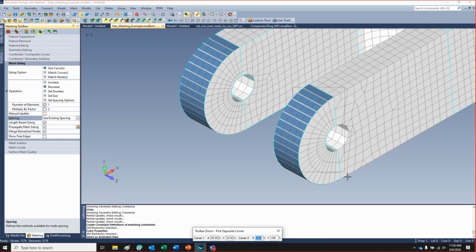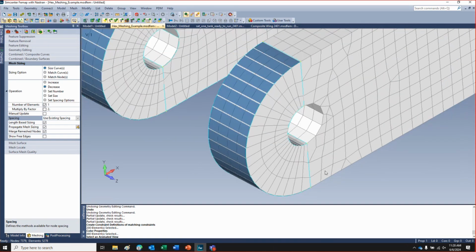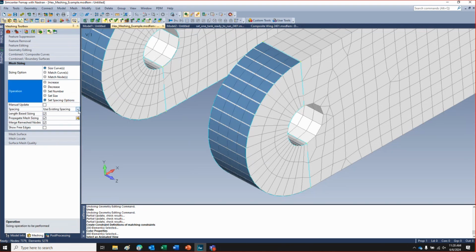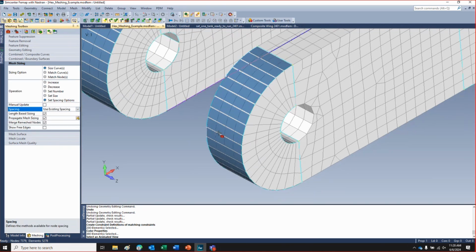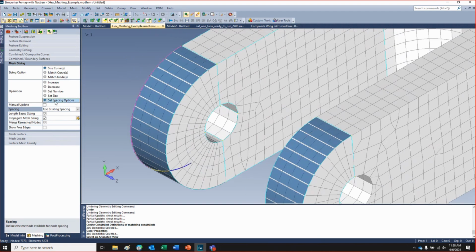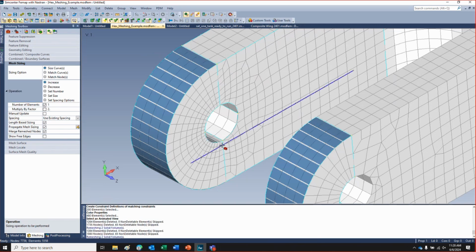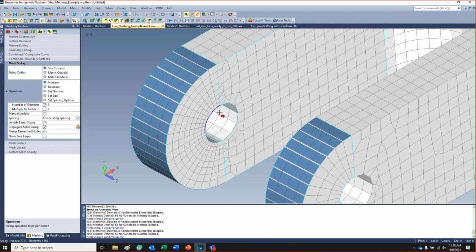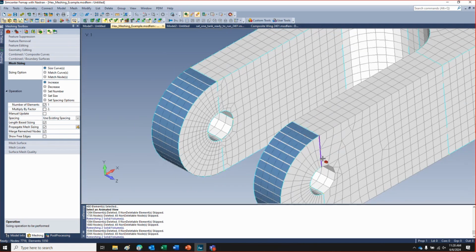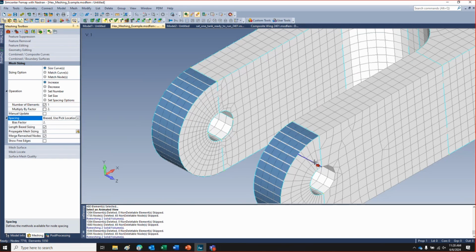And then the one last one, just so everybody knows what went on here, we did a bunch of stuff to make this better. If you just want to use existing spacing, well, let me set my spacing on. I'll just do it over here instead. Let's go to increase, use existing spacing. And you can see that now I don't have to respecify any type of biasing I might have. I certainly can go back to using the pick location and that type of thing.